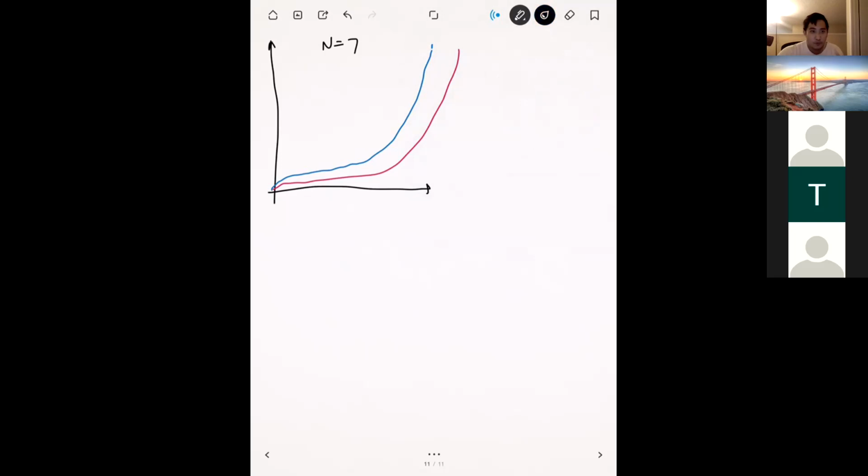But for this part of the class, I'm just letting you know that there's a trade-off in between. More realistically, what you need to know is that when you're working with commercial codes out there, you should learn about what kinds of schemes they use for particular things, because that choice of scheme is going to affect things like stability and accuracy. And so when you're debugging your simulations and trying to get them to match an experiment, you know which dials to press and what will affect what.